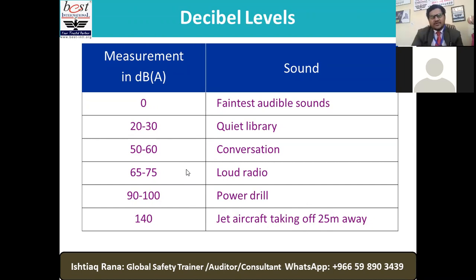even without a noise monitor. We don't work on assumptions. Bear in mind, guys, we as safety leaders never work on assumptions. Yes, when we have any project in confined spaces, then surely we assume, but still we double check. We assume there might be toxic gases, but still we double check with an authorized gas tester, with gas monitoring equipment, to reconfirm whether something is dangerous or it's all okay.